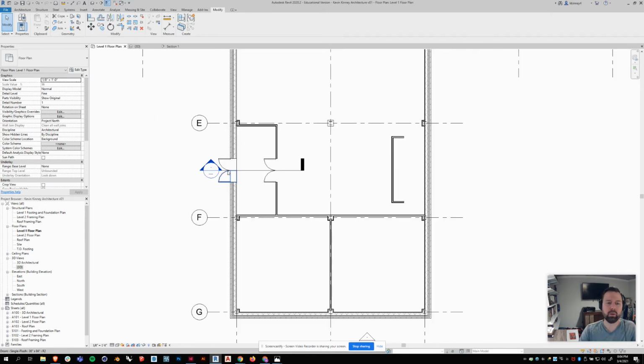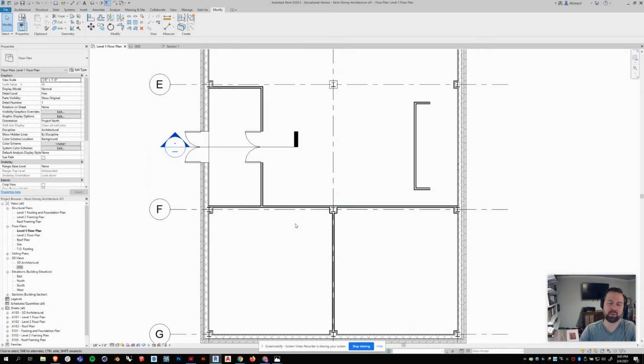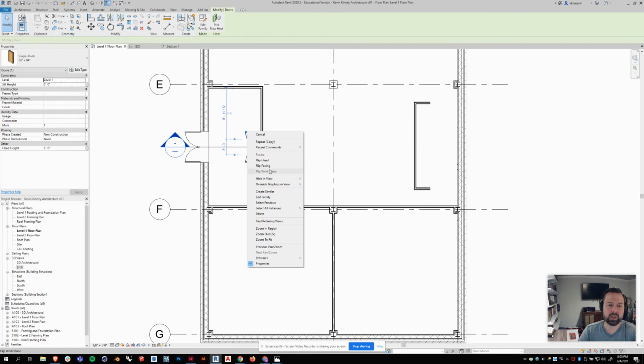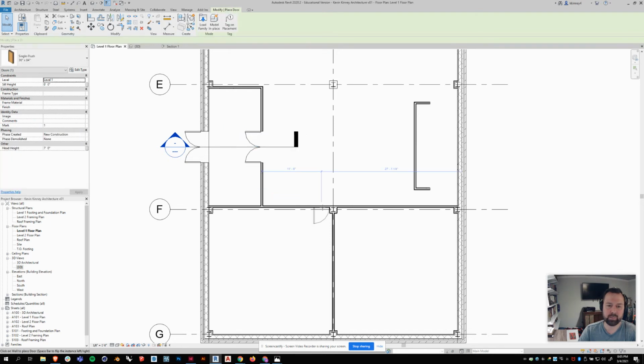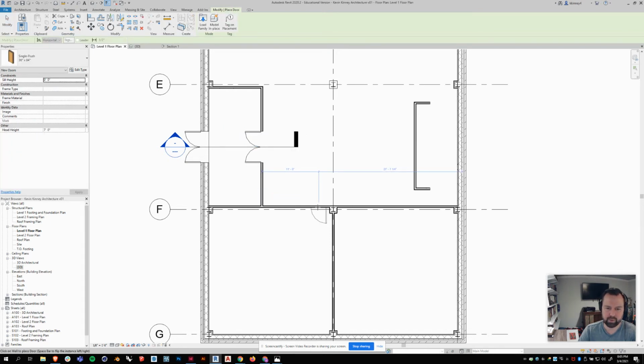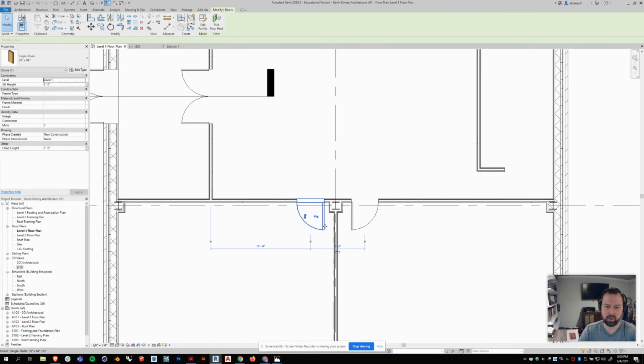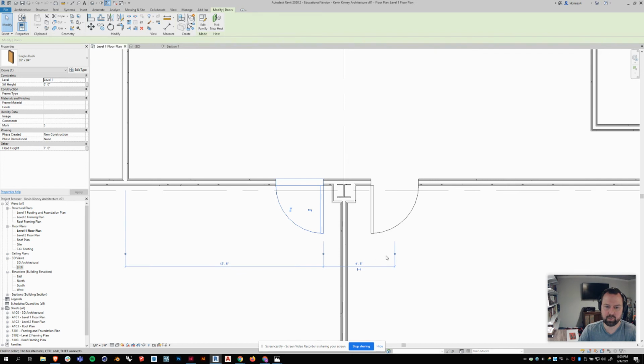Okay, so I've got my vestibule set up. Let's get a door into each of these conference rooms. Keep in mind, I might change this to be sort of a glassy entrance, but that'll come in when we talk about the curtain walls, the glass walls, which I haven't talked about yet. So I'll just grab one of these doors and right click, create similar, flip this guy around, flip this one around, and then position this where I want it.